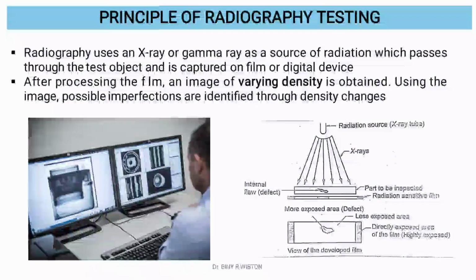Radiography testing is a method of inspecting materials for hidden flaws, defects, by using the ability of short-wave electromagnetic radiation to penetrate various materials. The density of the radiation that penetrates and passes through the material is captured by radiation sensitive film.